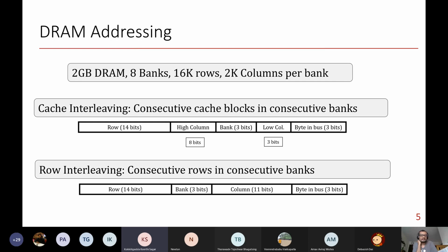In that case, I think the second case might be more advantageous because the entire row is already there in the row buffer, so I can just access a different column from the same row very quickly. Instead of trying to answer these questions, it all depends on the latency for each of these events, right?